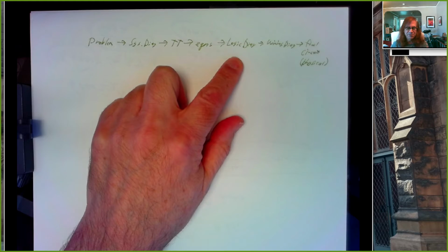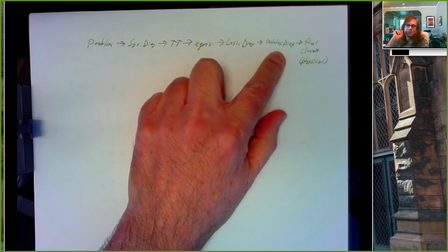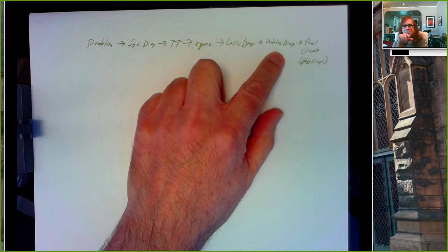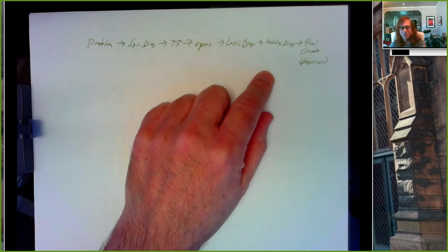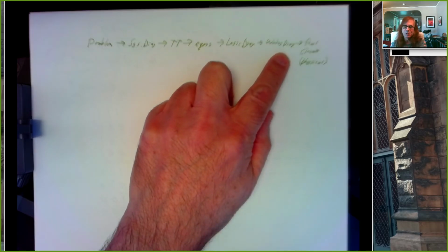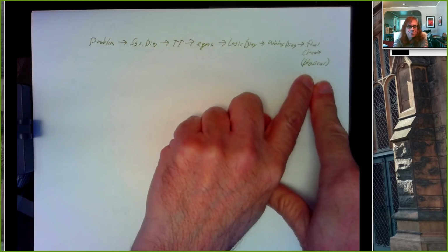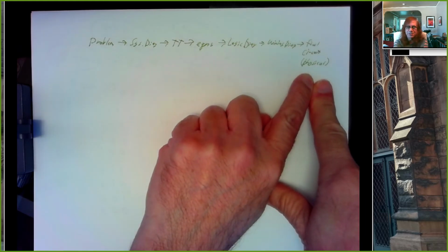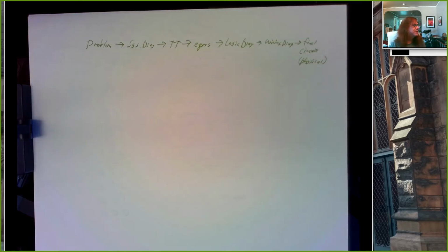The wiring diagram is where we have particular parts, not just an AND gate symbol, but we say this is a 74LS08, and pin 7 goes to ground and 14 goes to power, and this input goes to pin 1, and the output comes from pin 3. That's the actual thing we would use to put wires into a protoboard to build our circuit, and then the final circuit is the thing that we hook up to a power supply, and we flip the switches and the lights come on.